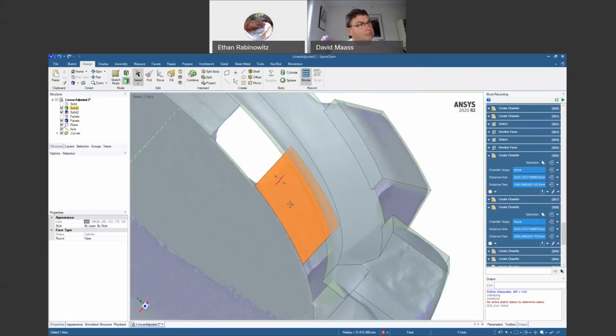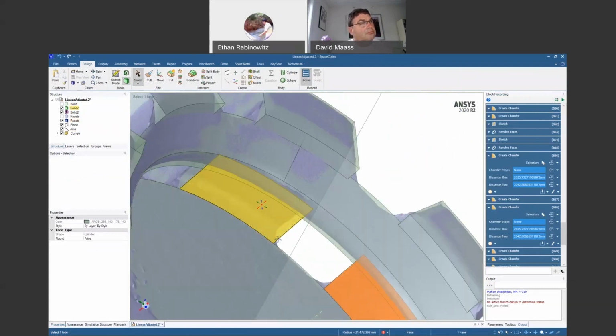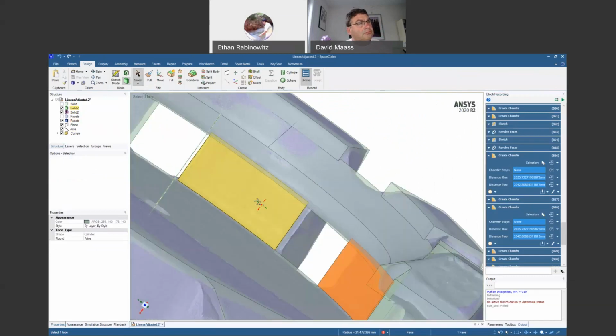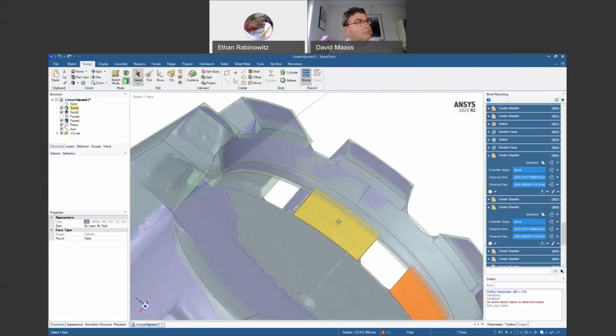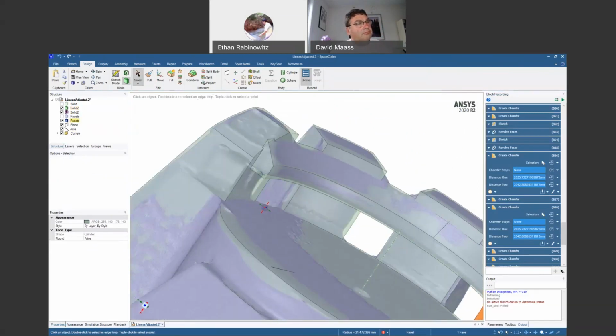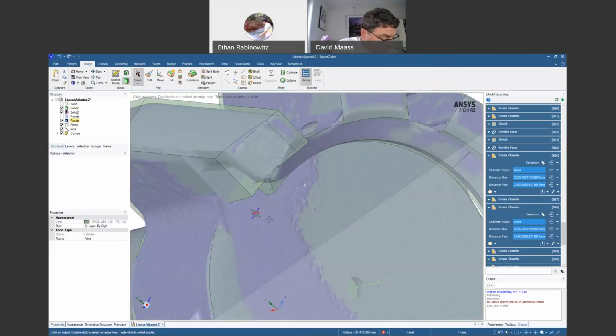And then I think the last big thing is the channel in here. Or wait, is the channel at different depths or did I not? Yeah, okay, so I haven't cut the channel. I just sketched this out to add the rib. So the next thing we would do is create a sketch for the channel and do a revolve cut. And it looks like there may just be some other chamfers or other sketches to add.